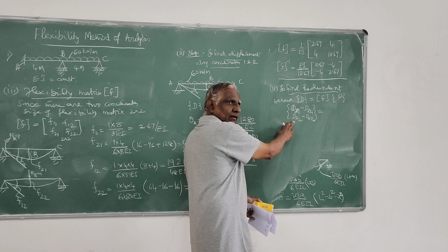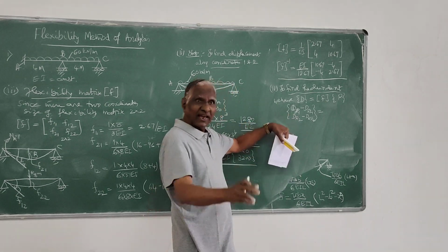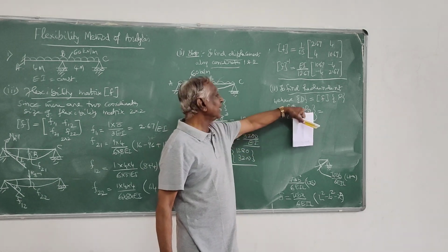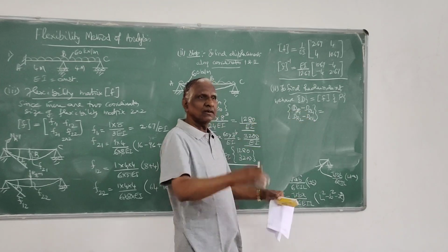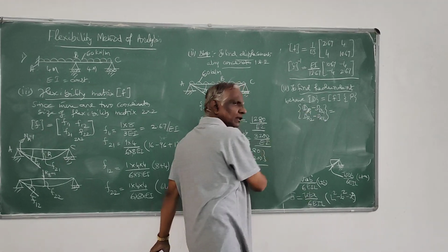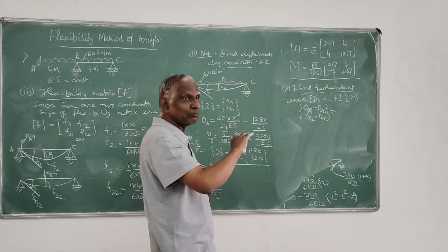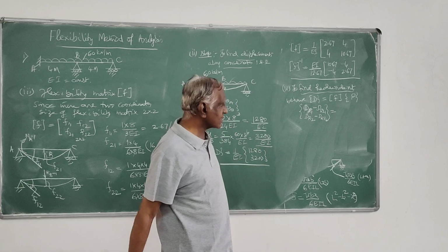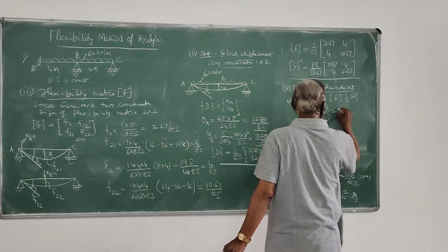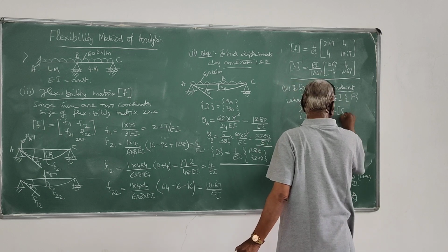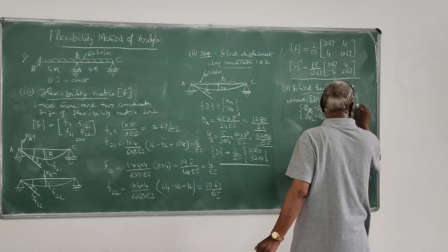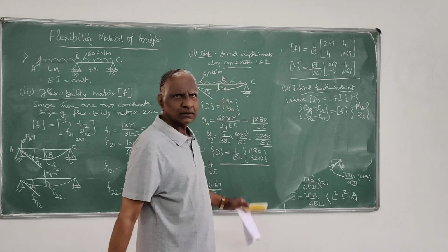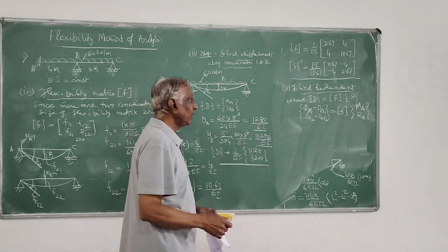Those are all joint loads. As in stiffness method, you have taken it as joint load. This is joint load and this is displacement due to given load. DRL1 due to given load, that's minus. There also PMF, minus PMF, you are taking. Here it is minus DRL1, DRL2 due to external load, that you have to take. And this of course F is there. And this P is nothing but your redundants, MA and RB. The two redundants, that is the value I have to take.